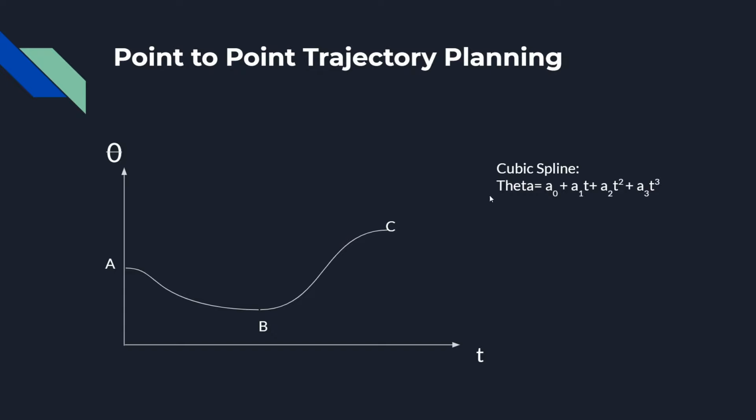But anyways, apart from cubic spline, if we differentiated it twice to get the acceleration, we would have a straight line for acceleration. That means there would be no control over the acceleration, the same way how we had no control for the velocity in case of linear variation of theta. We had no control over velocity.